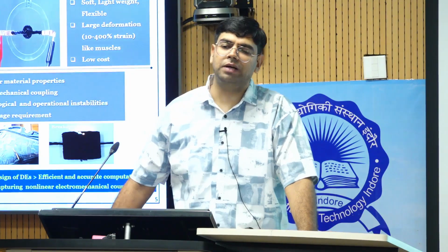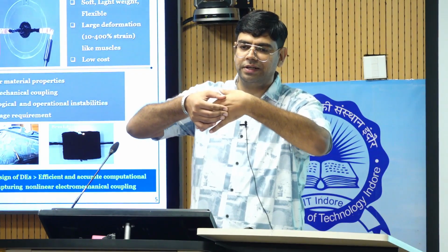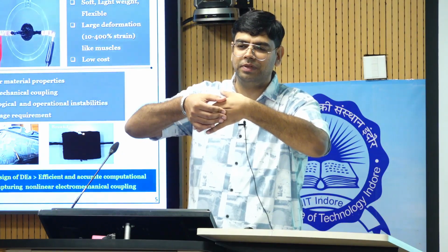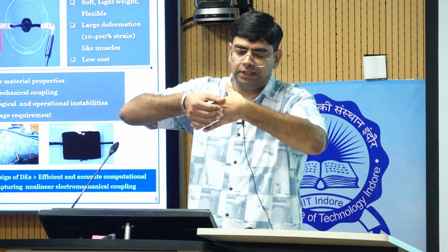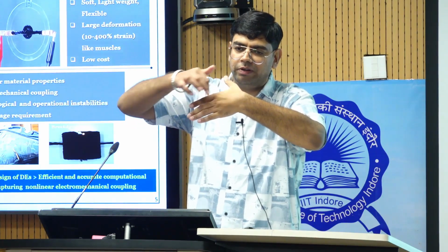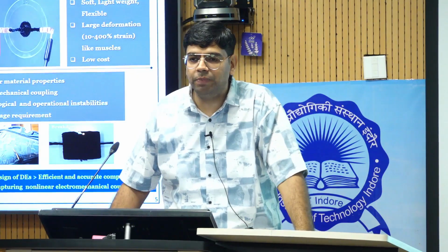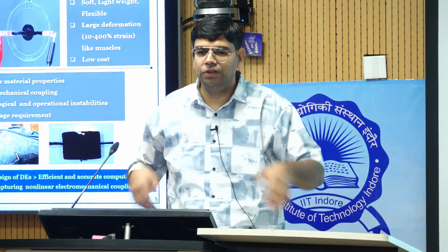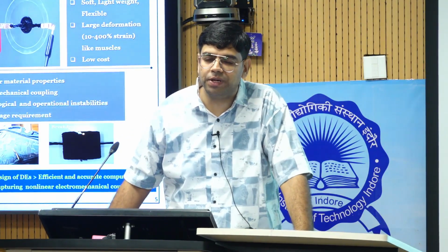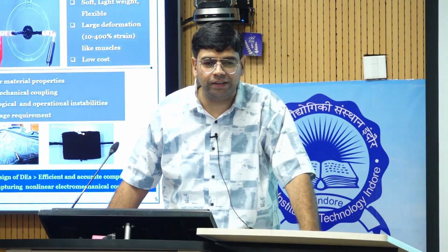Second one is, for example, I will discuss that thing in detail. If you provide some compression here at your hand, you can try this. The wrinkle will develop. If you provide some more compression like this, loosening the skin, some wrinkles will be developing. So what you are doing basically is providing in-plane compression. And to relax that in-plane compression, out-of-plane deformation is taking place in the form of a wrinkle.